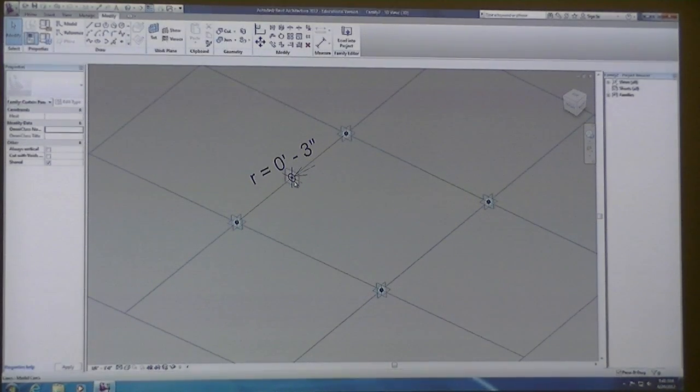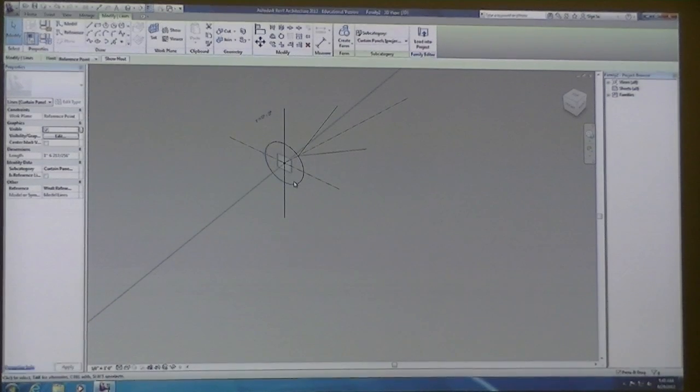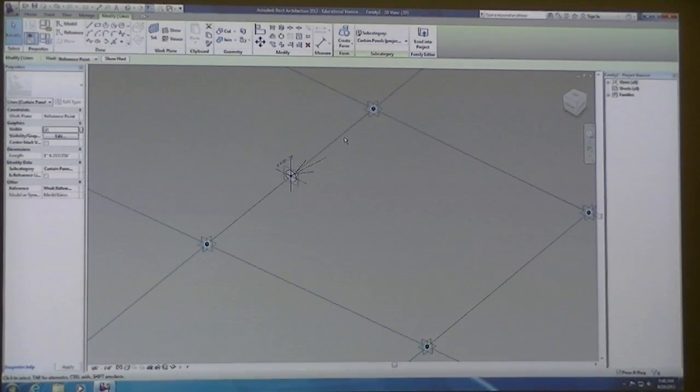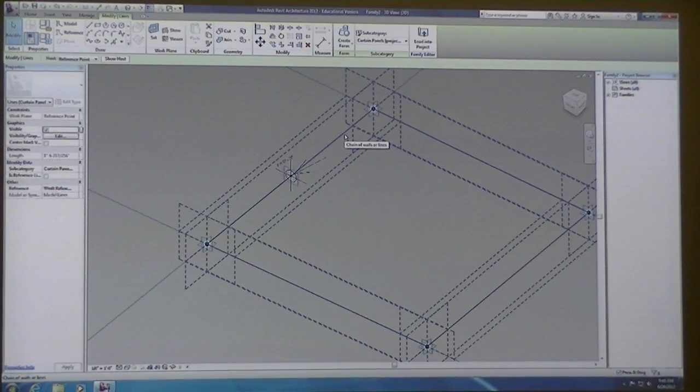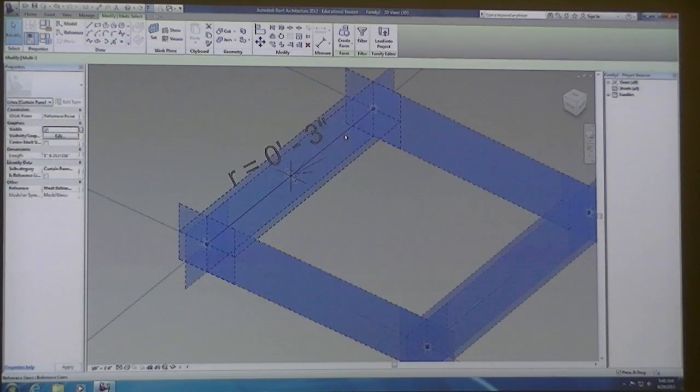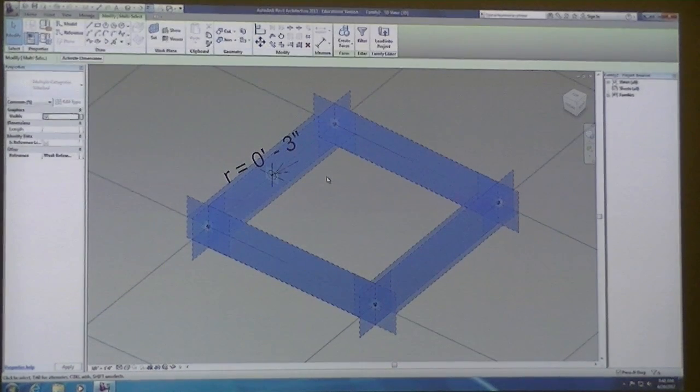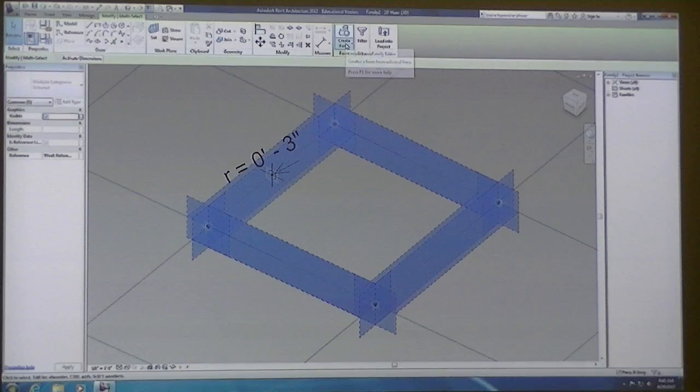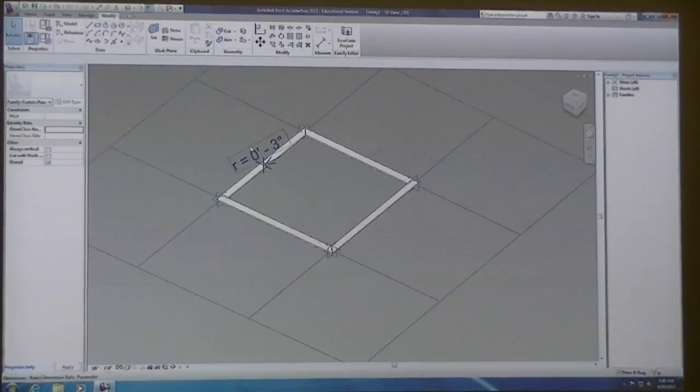The last step here to make this a pipe structure that goes around this whole entire form is to tab over until you can select that circle, and then hover over your reference line. You should be able to, because it's a reference line and it's all connected, it should highlight all 4 sides, and then we can select that and hit Create Form.